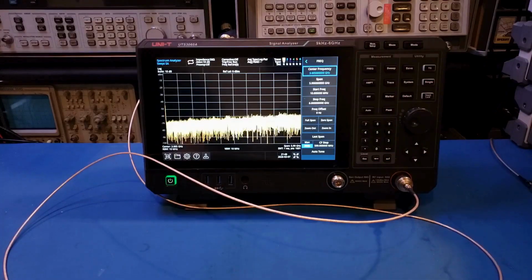So the main concept here is not that difficult to understand. Let's say we have 2 signals that are relatively close to each other in terms of their frequencies. If these 2 tones pass through an ideal system, obviously we would expect the same 2 frequencies coming out, except perhaps they are stronger than before if they pass through an amplifier. But in the real world, there's always going to be some nonlinearity associated with amplifiers. So as the 2 signals go through the amplifier, due to the nonlinearity, intermodulation products would be present at the output. Let me try to explain on paper.